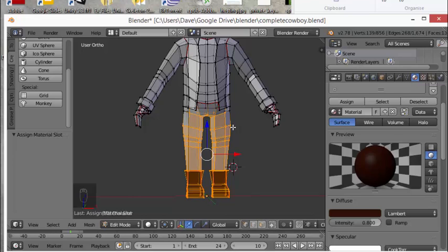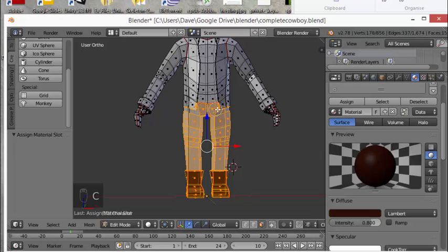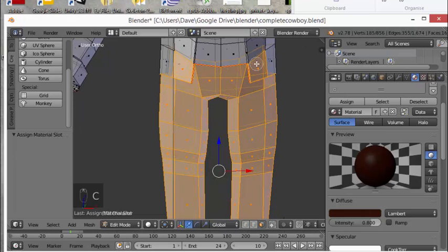So box select again, and I've turned on the brush select tool with C to try and grab the rest of them. I really need to be on faces mode though, rather than edge mode. If you select something you don't need, then you can use the middle mouse click to deselect. So let's get faces mode on. Right click to knock the tool off, faces mode, and then we'll over select things like so. And we've got X-ray mode on now, so it's just a case of right clicking or middle mouse clicking with this tool here.